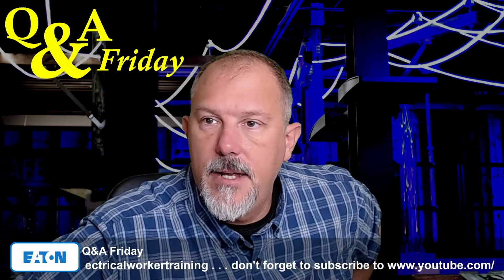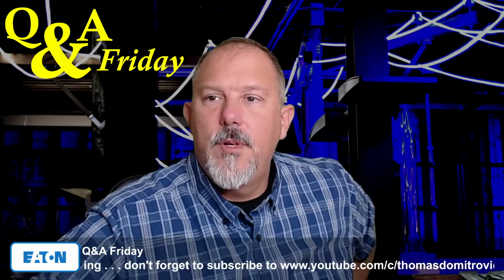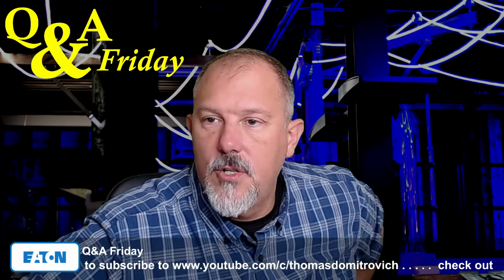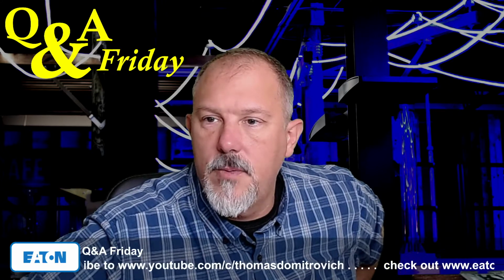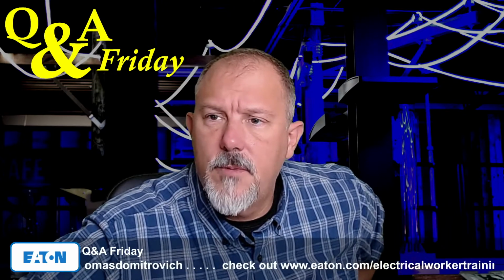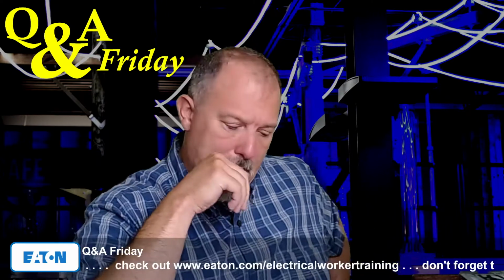Putting the GFCI, so it's not enough. Yeah, so I'm glad you're online, JW, and you're chatting up a storm. That's kind of cool. I'm aware of the difference between outlet and receptacle. Well, that's a good thing. So if it says for outlet, then a GFCI receptacle is not allowed because it must go ahead of it. And you know what?